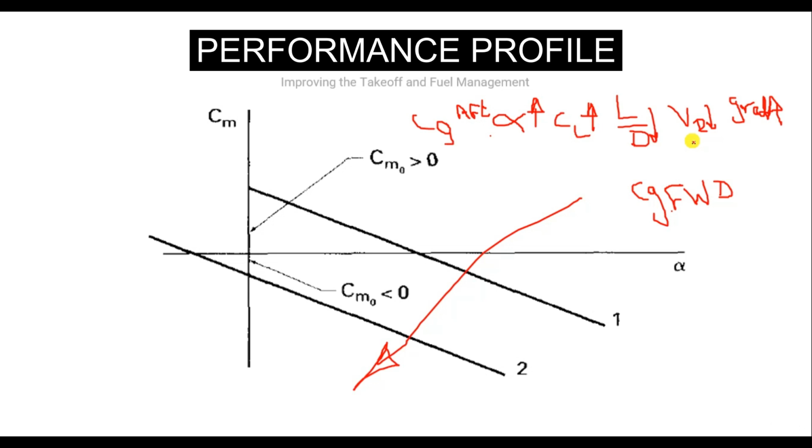I can extend the length of the runway and take off with much less speed, or I can take higher weights on board the aircraft. So it's a benefit, but with less stability. You don't get anything for free in life. It's less stability, but higher performance, better fuel consumption, better economics, better utilization of your aircraft.